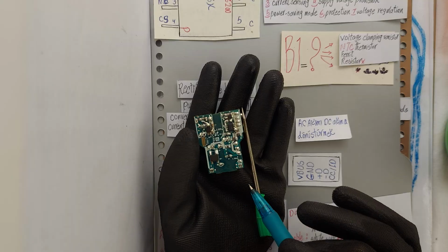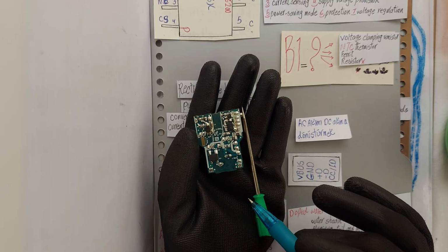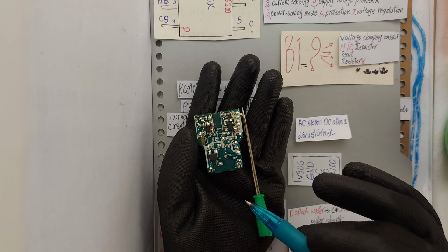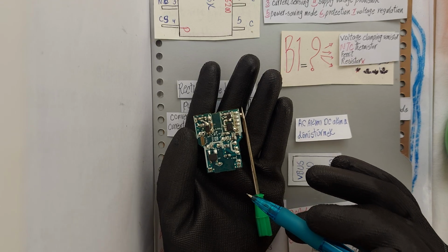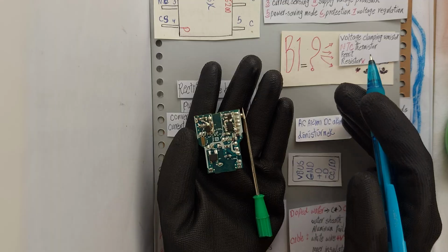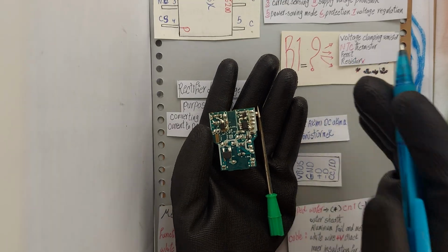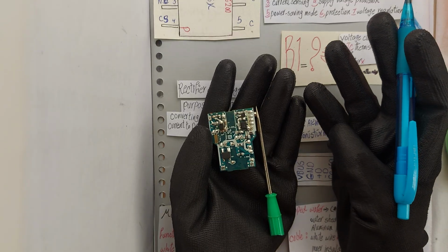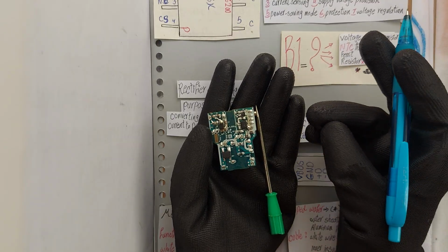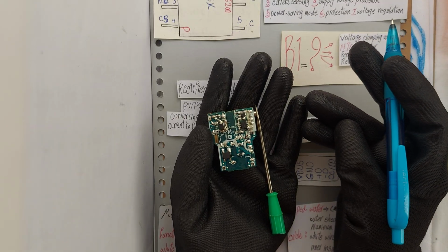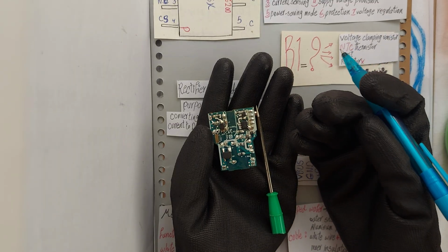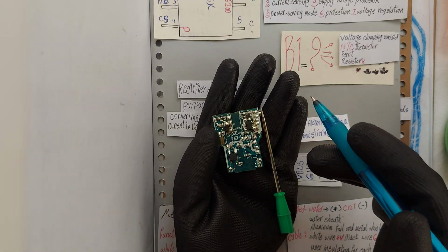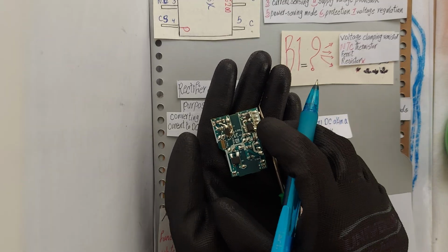However, based on its position, a resettable fuse is also a plausible option, especially if the circuit designer prefers overcurrent protection. So, in summary, we conclude that B1 is likely one of these three components: a ferrite bead for noise suppression, an NTC thermistor for inrush current limiting, or a resettable fuse for overcurrent protection. If you see a similar component on your board, now you know what it might be.